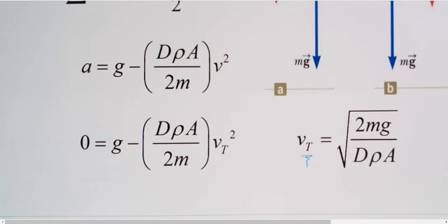That means when you hear that this car's maximum speed is 200 kilometers per hour or 220 kilometers per hour, how do we determine that? Well, the maximum output of the engine will be equal to the drag force, and considering density of air and the cross section, you then reach the maximum speed of the car.